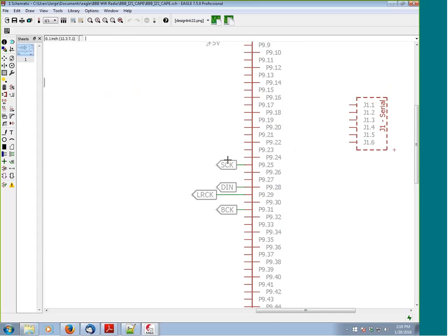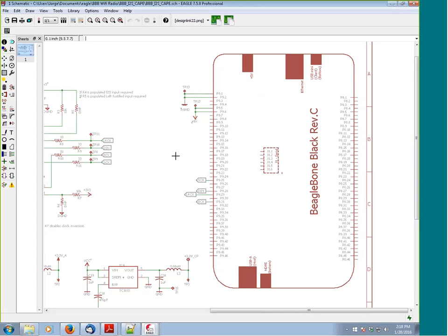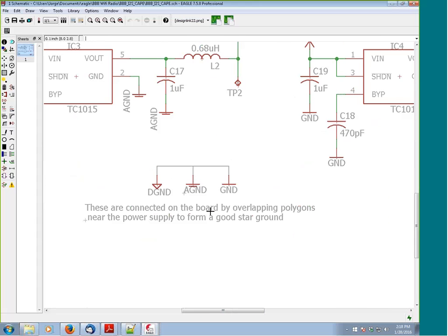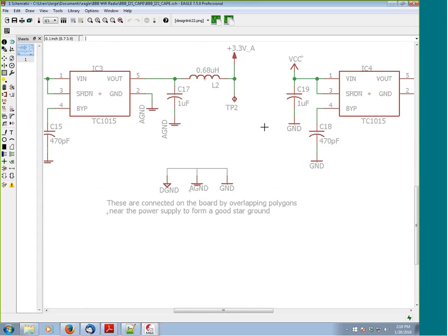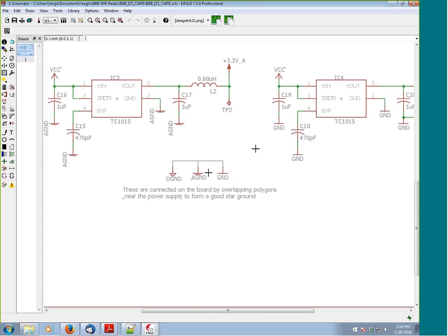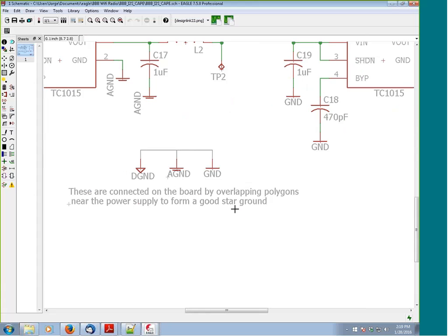Okay, and over here you can see all the signals as they connect and they go over here. And the power. The last thing I want to mention on the schematic is this over here. Very key point. In Eagle, all the connections are defined by net name. So in order to connect nets that have different names together and still preserve the separate names, you have to do some tricks. There's a lot of ways this can be done. Some guys will create jumper libraries, and they'll basically be 0 ohm resistors. On the schematic, they'll show up as resistances or whatever symbol they choose to use. And then on the board, the actual layout, it'll be a part made up of 2 SMD pads shorted together. So as far as Eagle is concerned, there's 2 connection points, but the reality is that they're shorted by the copper. That's one way to do it. In my case, what I chose to do is put an explanatory note here and then do the connecting of the 3 grounds on the board, which I will show you guys when we go to the board.